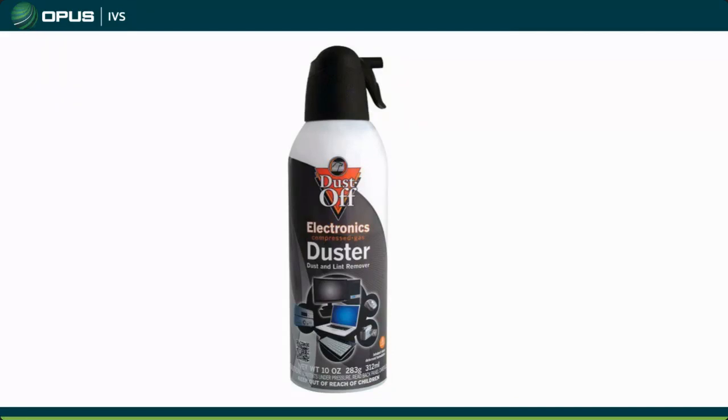Now, why do I have a can of dust off here? Well, whenever I talk about these cyclones, obviously in that picture, that was kind of a representation of one. Those cyclones are very small. And when you have air, a gas, moving through a fixed orifice, just as when you are using your dust off here to blow stuff, that gets very, very cold. You have a gas going through a fixed orifice, very small. When that gas expands, it pulls your temperature down, right?